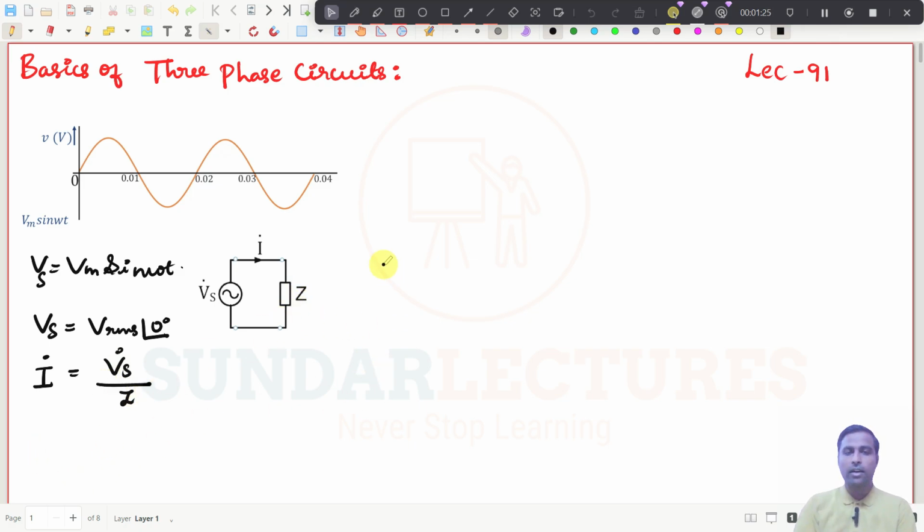And also we can write the power formula. P is equal to V into I cos theta. If this is Z, then Z will be at an angle of some theta. If it is an inductive load, then Z is equal to R plus jX, and if it is a capacitive load, then it is R minus jX, right? All those things we have already studied.